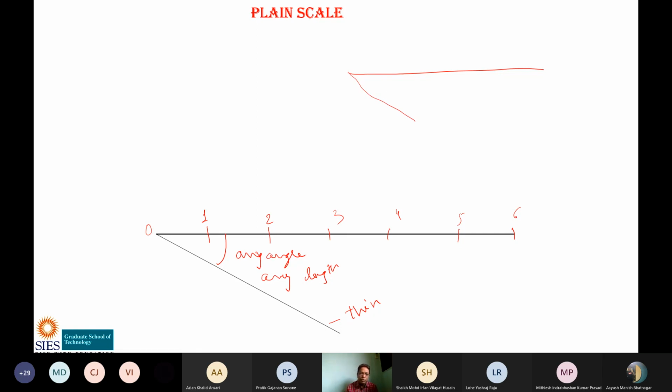I think students, you are also doing it with me. Now how many parts do I want to divide this line into? 6 parts. So this line also I will divide into 6 parts, but not approximately. I will use the compass and draw arcs. I will take a suitable distance in the compass, any distance, but this distance I am not going to change every time. The same distance, and I am going to draw an arc.